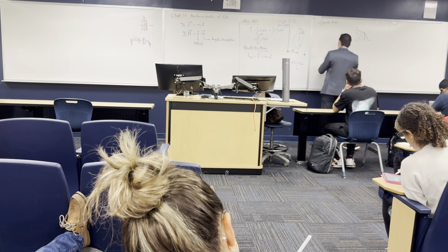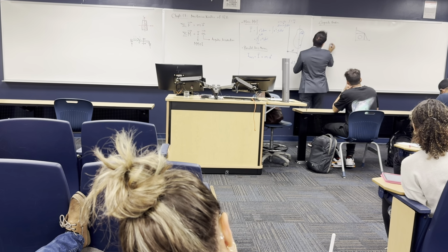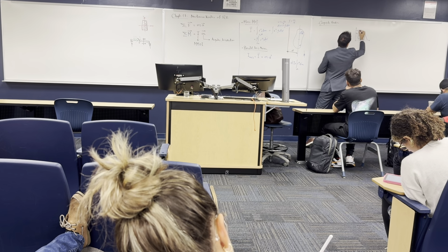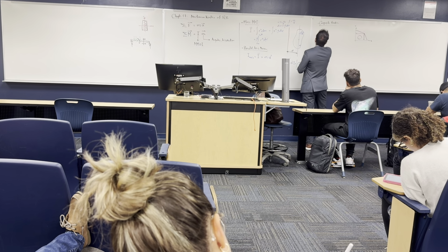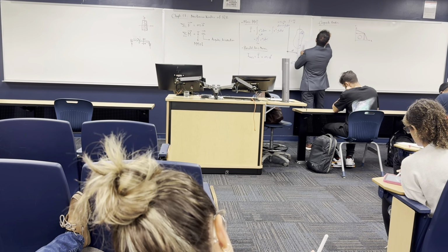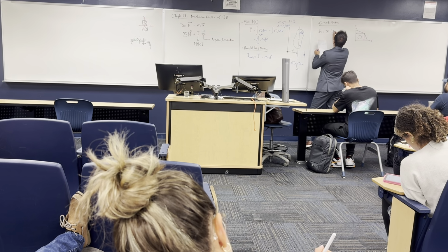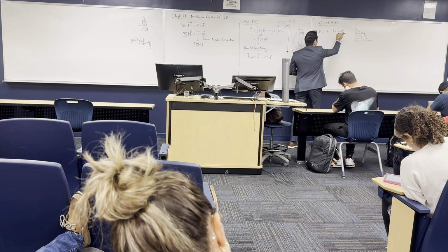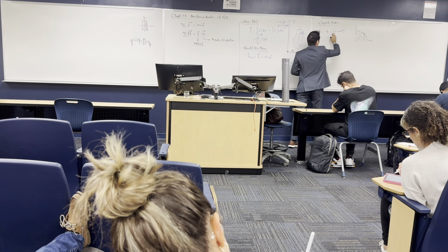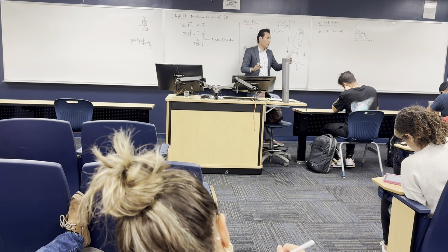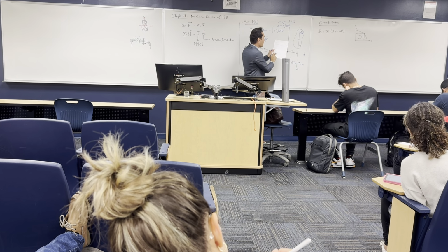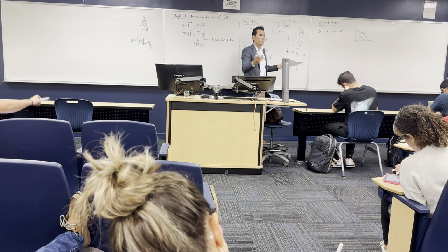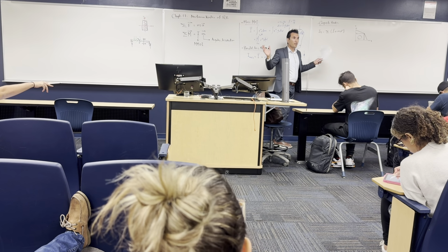So to get the mass moment of inertia, for example, about this axis, let's say xy, if you want to get Iy, you have to get the summation of the I bars plus md squared. But this is plus md squared, and like always the mass moment of inertia is positive. All mass moments of inertia of positive masses are positive. But you will tell me, is there a negative mass? Yeah. Mathematically, yes. Physically, no.